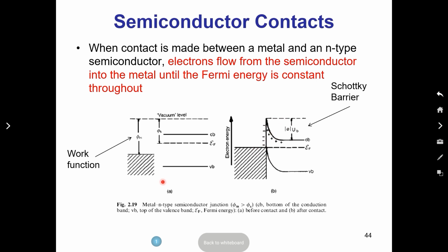So when you are measuring the conductivity of the samples, you don't want a Schottky contact. But people use Schottky contacts as a device. So for example, if you create a Schottky contact and expose it to some gas, like hydrogen or carbon monoxide, or an oxidizing gas, and so on, depending on whether it's a reducing or oxidizing gas, it will actually modulate that curve.